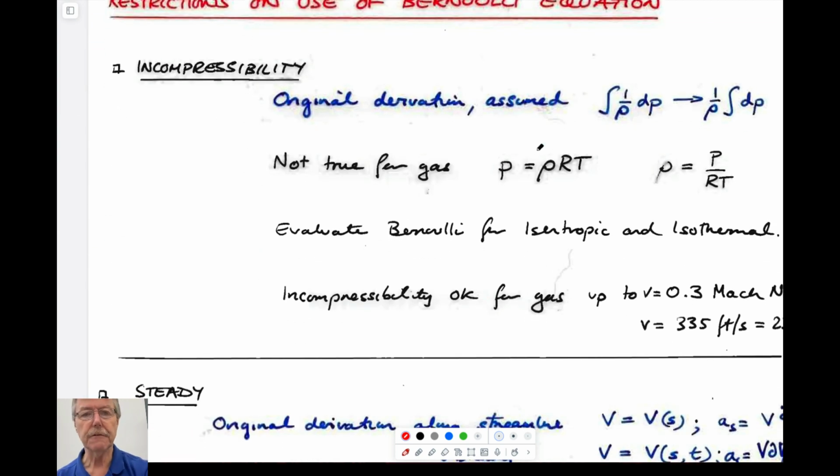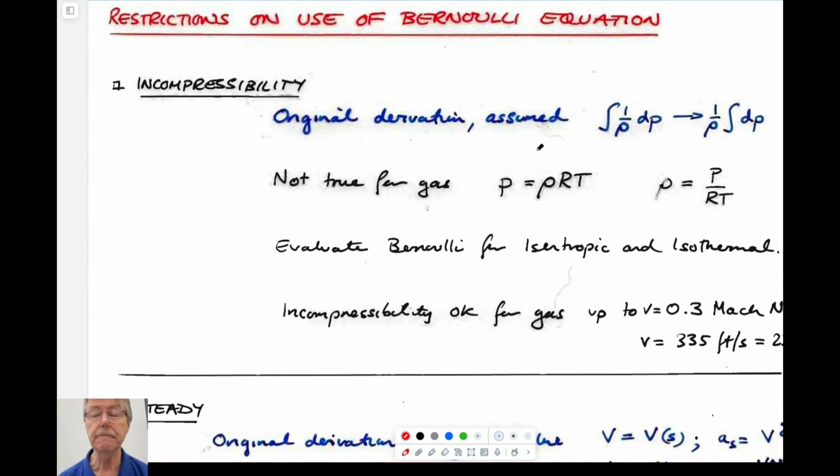And, well, all these interesting facts kind of have some relevance. So that's our way of looking at Bernoulli. Think of it as an energy grade line which is horizontal, and that upstream and downstream they have to match each other. Bernoulli is useful. We can use it to do these rate measurements for flow rates in pipes and flow rates in weirs by using Bernoulli and using the continuity equation to link the two areas upstream and downstream by specifically assuming that the upstream velocity is not zero.